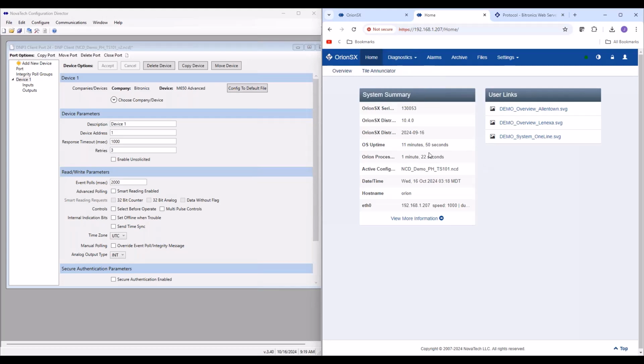If you've got something set up in a configuration file and you haven't actually been keyed for using that protocol, it will throw an alarm, and you can sort through the logs and it'll tell you exactly which port that error is occurring on. So that's a quick demonstration on troubleshooting communications.